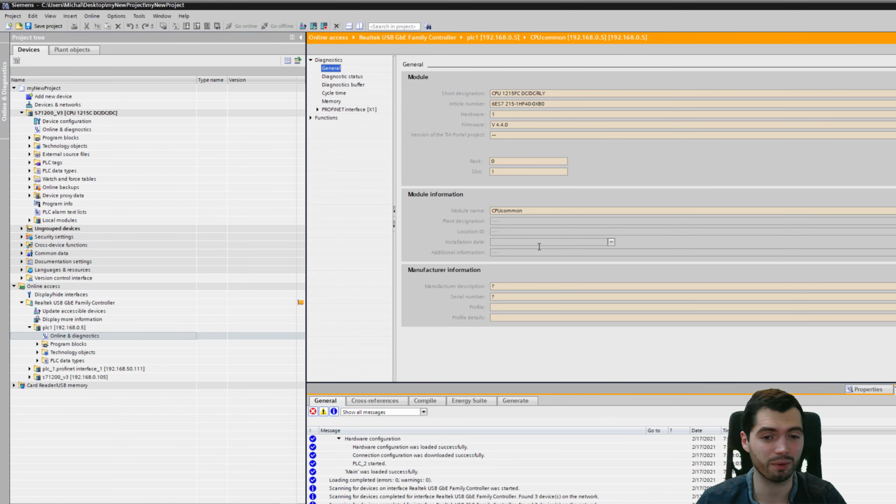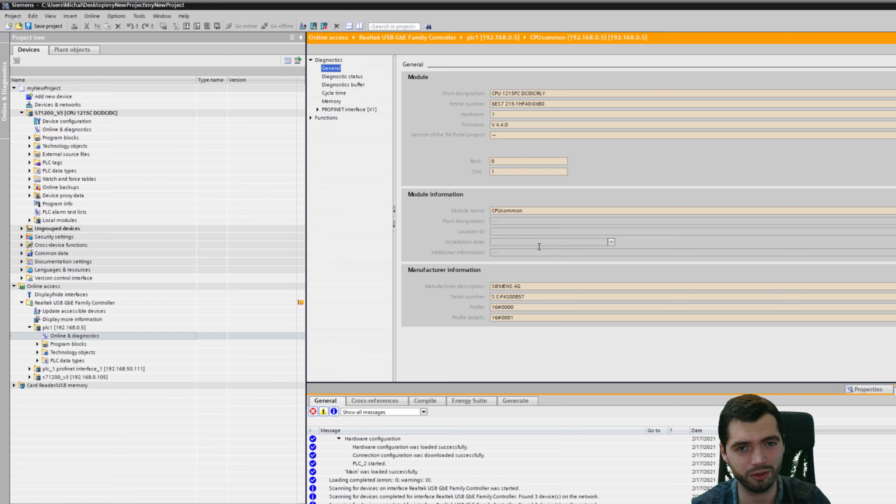And it is, okay? So as I mentioned before, PROFINET uses layer 2. For layer 2, what is important is the MAC address, but what is important for PROFINET is the actual PLC name, and it is the name that PROFINET communication actually uses to talk to other devices. And you will see this problem most often with drives. If you have a fresh new drive like a SINAMICS G120, if you don't give it a name, you will not be able to connect to it. And this was exactly the same case.